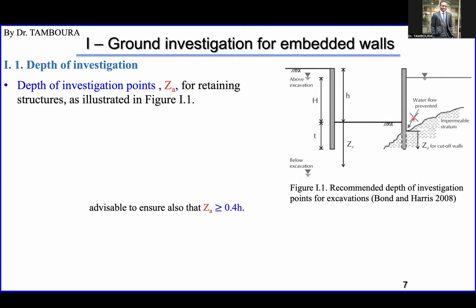So for each case, you will have a different value of ZA. Remember, what is ZA? The depth of investigation, how deep you need to go, because you need to know what type of soil you have on your site before you build anything.